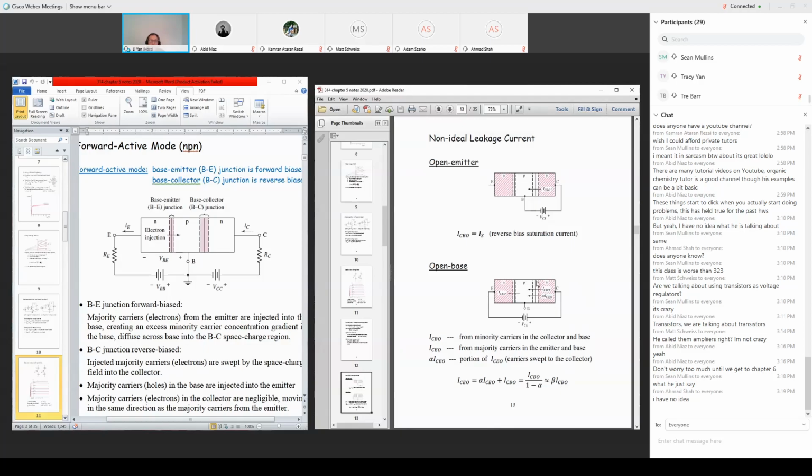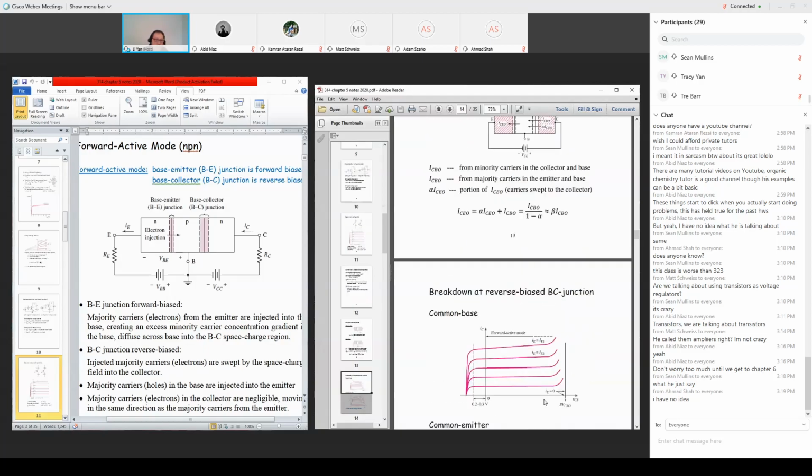That just says the dark current or leakage current here is ICBO, IS is 10 to the minus 15 amps. But this current will be stronger. How much stronger? About beta times stronger. Still, it's very small. Yes, it's about 100 times stronger in the second situation, but nonetheless 10 to the minus 15 amps times 100 is still leakage current.